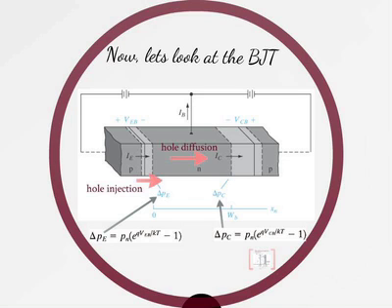When reverse bias happens, this was on your midterm, I believe, carrier extraction happens, right? You pull away the minority carriers from one side. And you have a situation where the concentration of holes here, which are the minority carriers, is now determined by the reverse bias voltage, VCB.